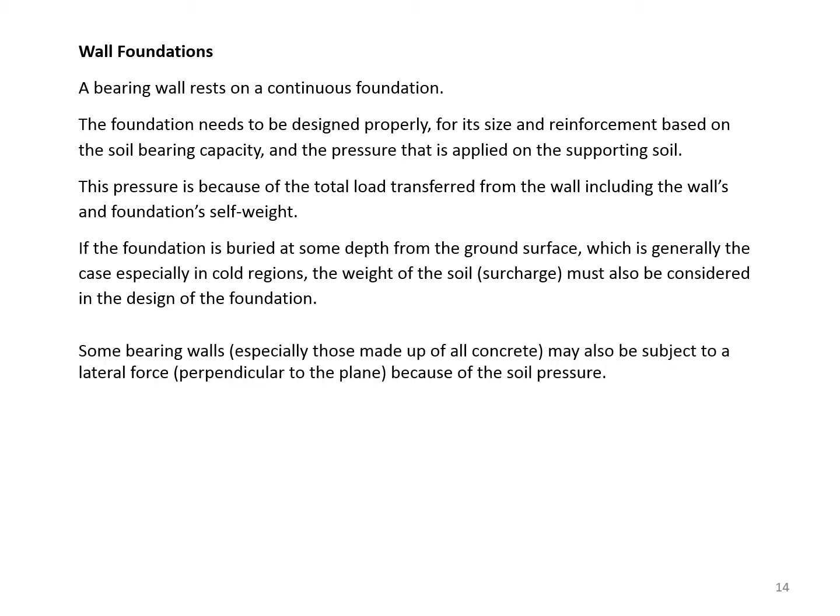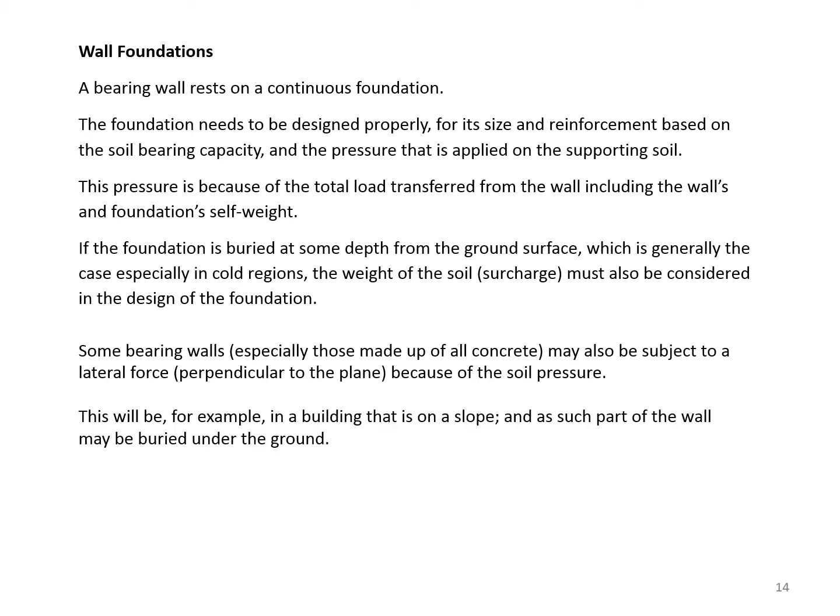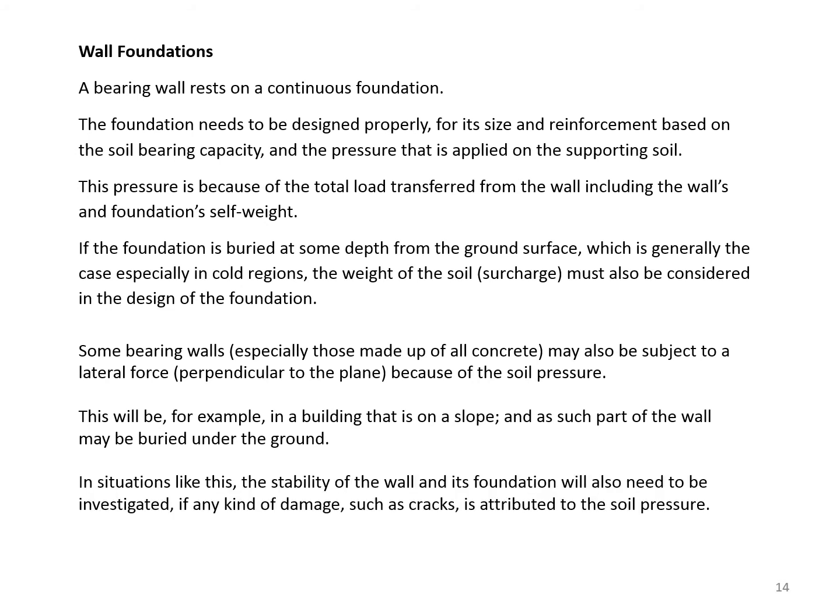Some bearing walls, especially those made up of all concrete, may also be subject to a lateral force perpendicular to the plane because of the soil pressure. This will be, for example, in a building that is on a slope, and as such part of the wall may be buried under the ground. In situations like this, the stability of the wall and its foundation will also need to be investigated if any kind of damage such as cracks is attributed to the soil pressure.